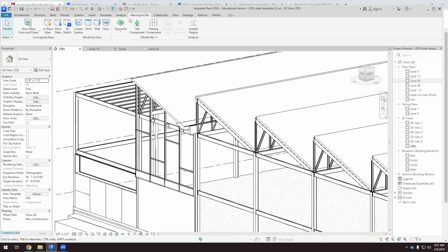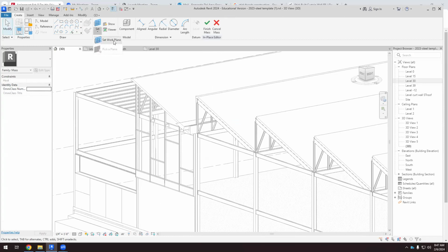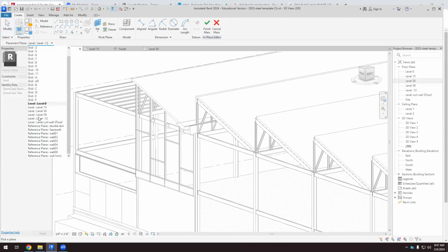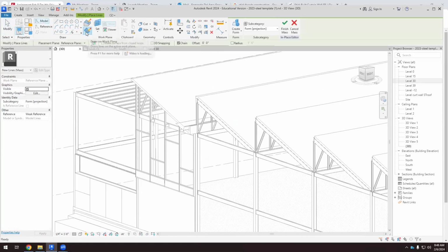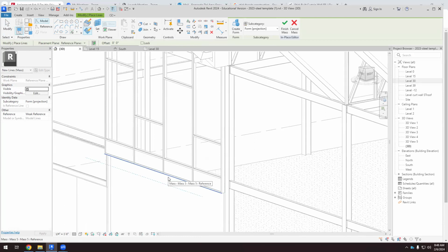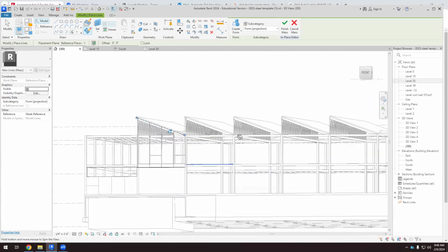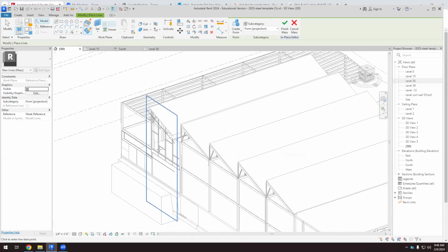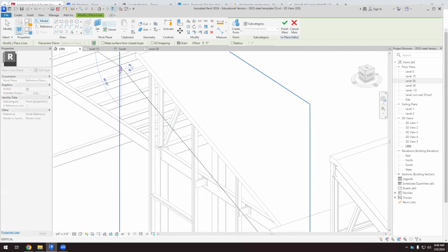We're going to work with massing and site, in-place mass. We're going to set the work plane at the double skin. I'm going to use model line, and I'm going to activate this draw on work plane. So if I do this and I pick lines, I pick the bottom line of this curtain wall. That's it. I pick the bottom line of this roof. So now we have these two lines. And now I'm going to connect this line and that line and this one